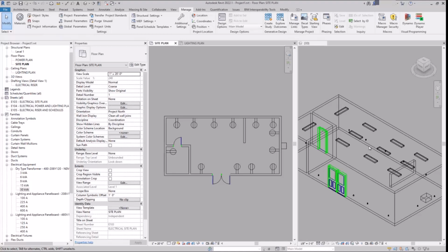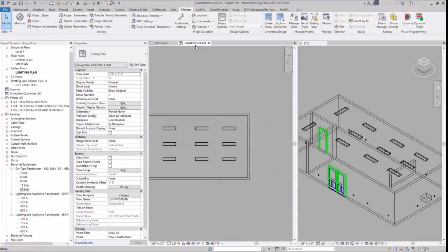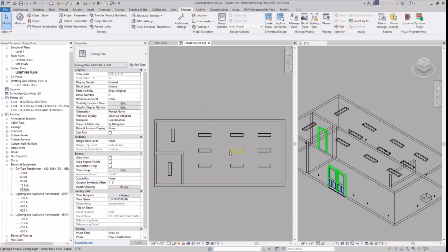Like office buildings are supposed to be 40 to 50 foot candles 4 feet above finished floor. Exit egress paths have to have like 0.1 foot candles when all the power's out. So we have to have emergency lights, like bug eyes and whatnot. So while the architect goes, we want this, engineers go, you actually have to have this based on code requirements. And I literally just kind of threw this in here because of experience. So I kind of just know how this would lay out.